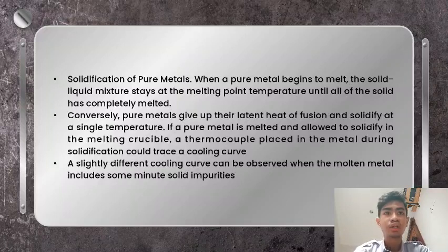This is because commercial melts always contain some sort of nucleating agent. Most often this agent will be the wall of the mold itself. However, other agents may be deliberately added to the melt to control nucleation and the degree of undercooling. Such additions are especially important in controlling the solidification characteristics of certain alloy castings, such as cast iron, for example.